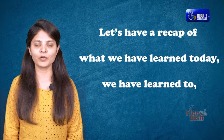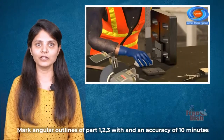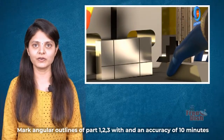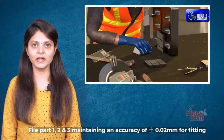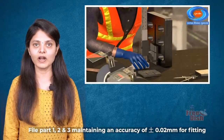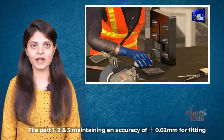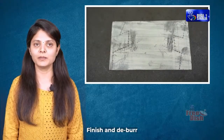Let's have a recap of what we have learned today. We have learned to mark angular outlines of part 1, 2, 3 within an accuracy of 10 minutes. File part 1, 2, 3 maintaining an accuracy of plus or minus 0.02 mm for fitting. Assemble the part 1, 2 and 3, finish and deburr.